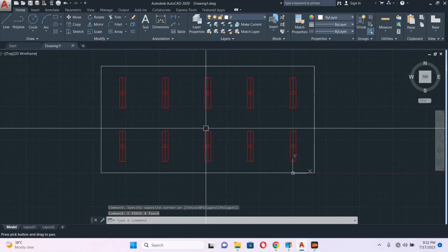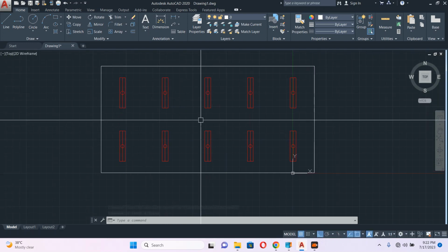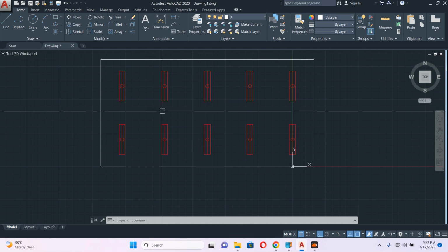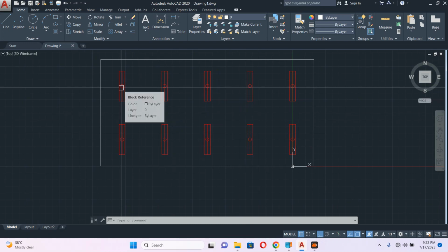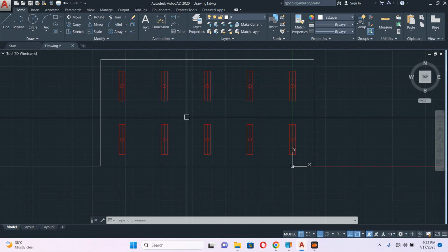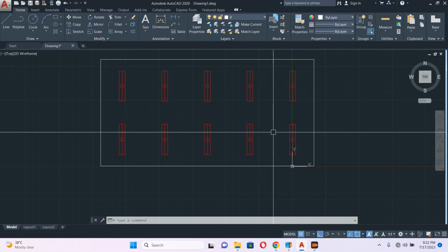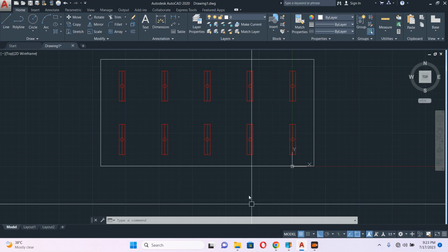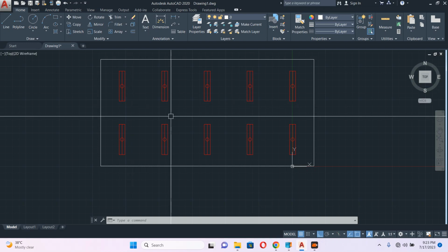So how do we divide these lights? As per Gulf standard, actually Qatar standard, in each circuit you can put 18 points of light. So here I have 10 lights. So these 10 lights I can put on one circuit.